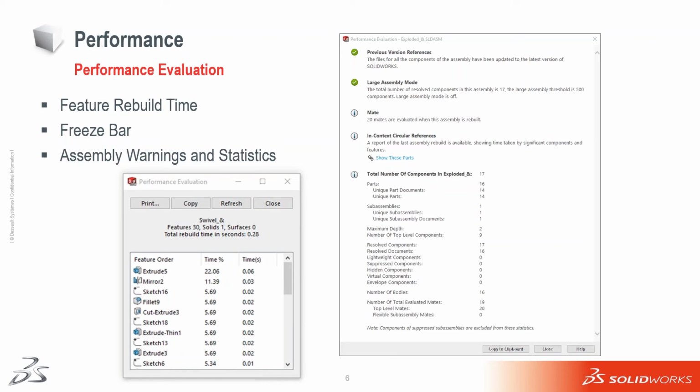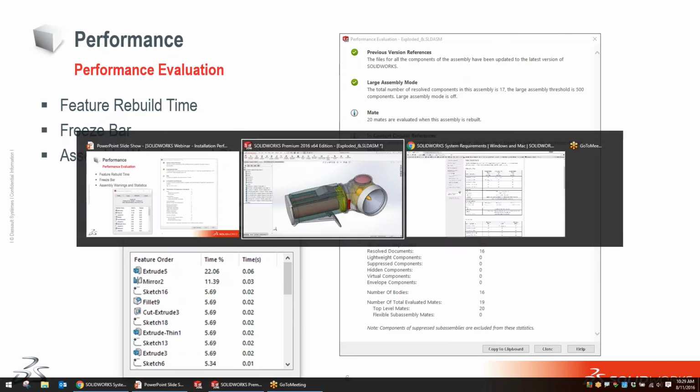Nobody else can make edits to the network copy while it's there, but they can still see it and open it as read-only. And then when you check it in, it puts a copy of your local copy onto the network as a version. It has full version history capabilities and permissions options as well, but it really does help to address network performance issues, SOLIDWORKS PDM.